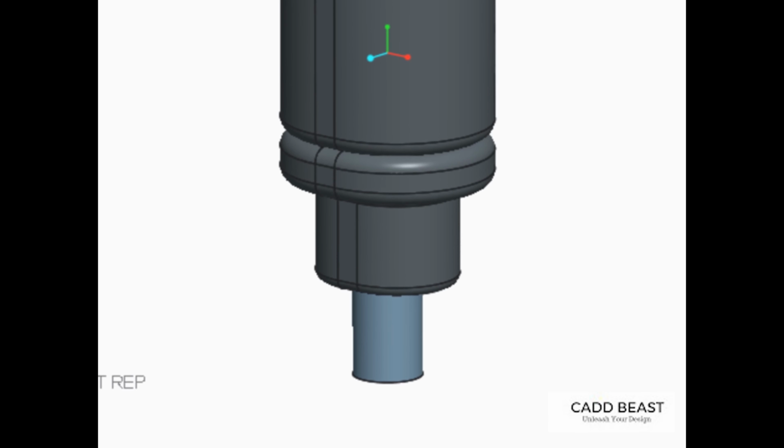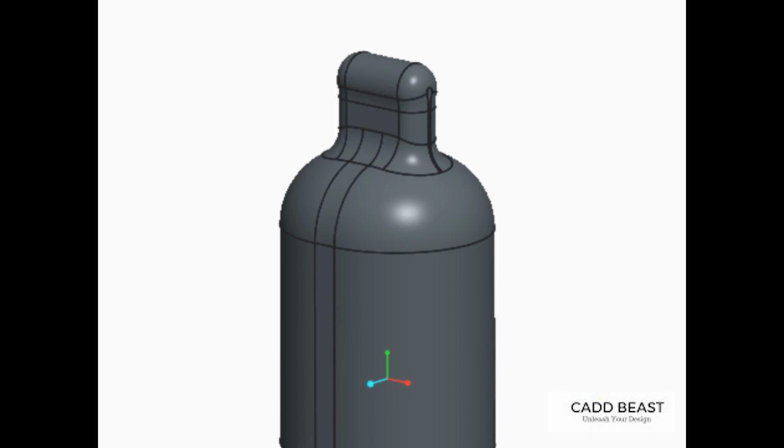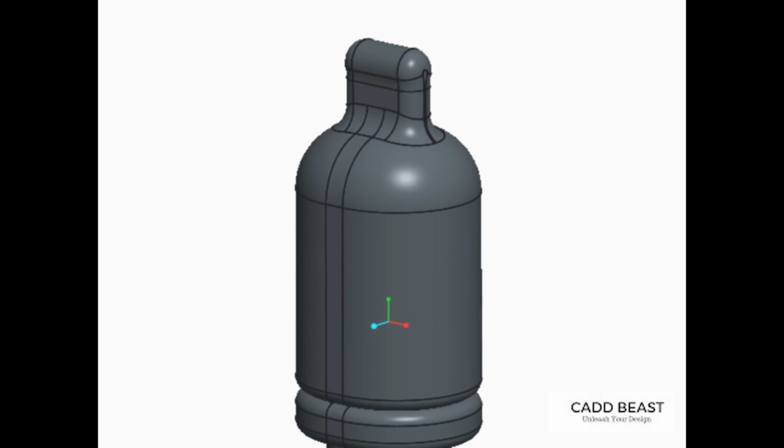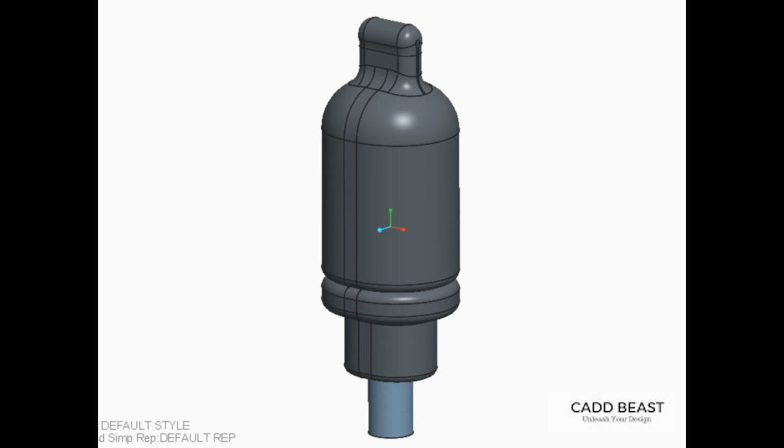In Creo Parametric, you can add flexibility to any component that has already been placed in an assembly. Many designs contain flexible components, such as springs, clips, rubber washers, and so on.